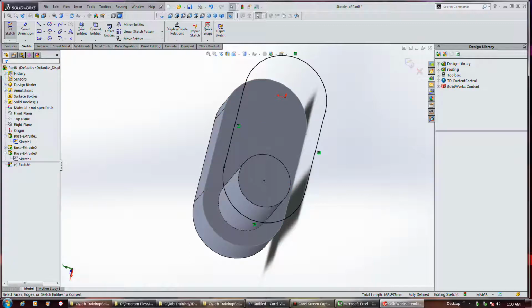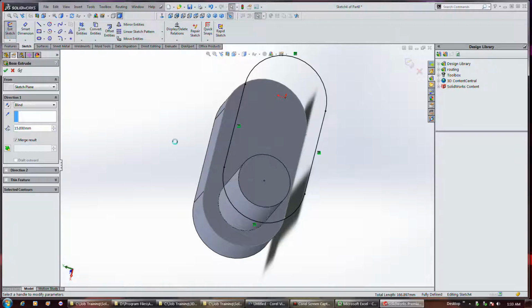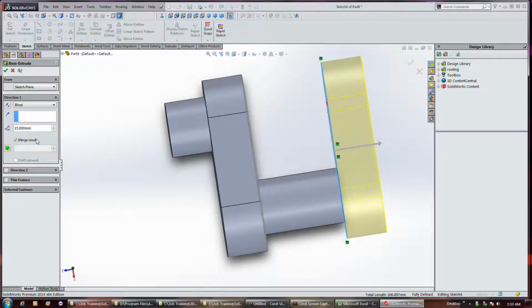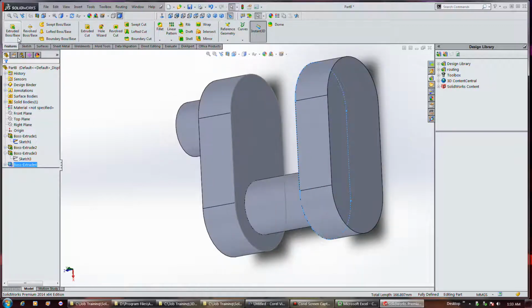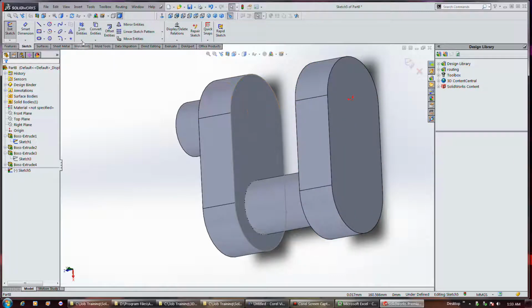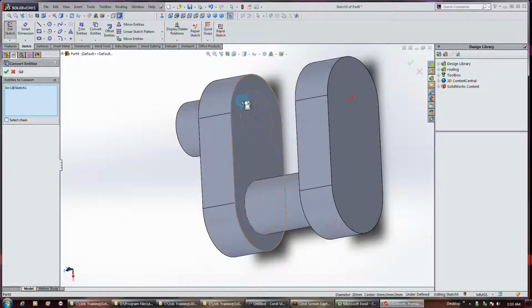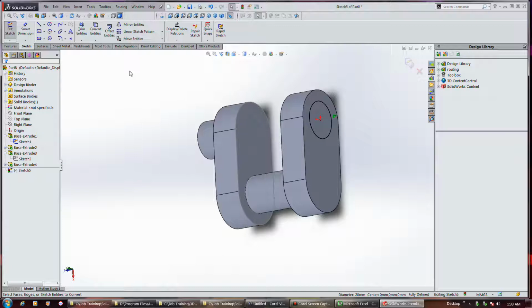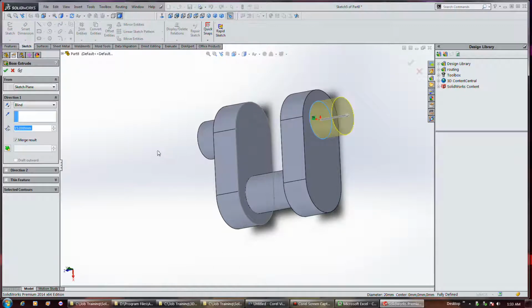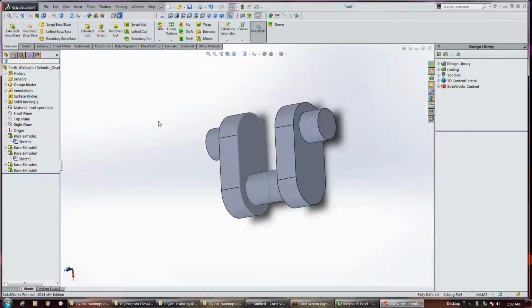Okay. All right, exit sketch, and I think I made this one 15, so that's fine. I'll repeat that. And I'll make another extrusion on this thing, and go convert entities, and bring this in. So, and go extrude that by 15 as well. Okay, so anyway, basically I made a solid body here. This part, right? Okay.